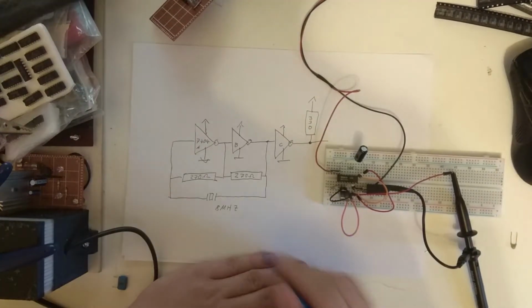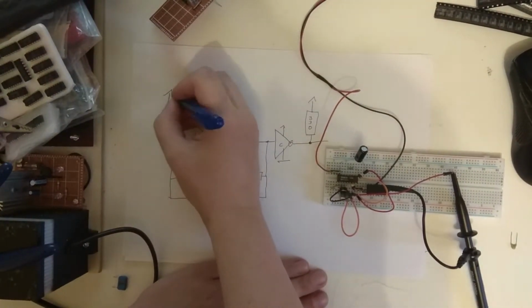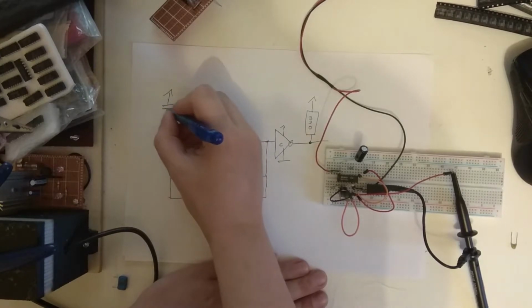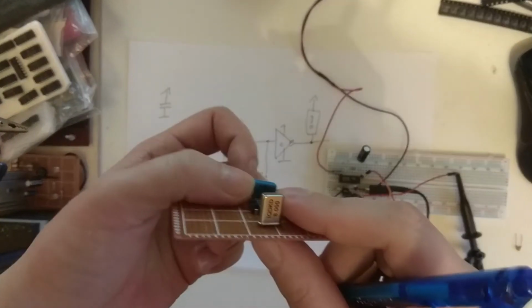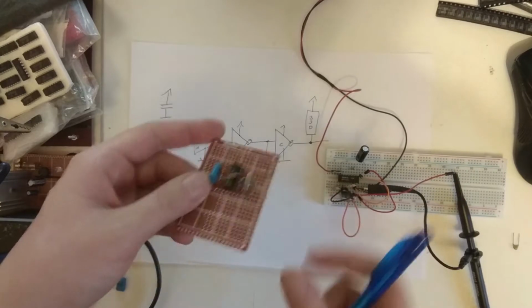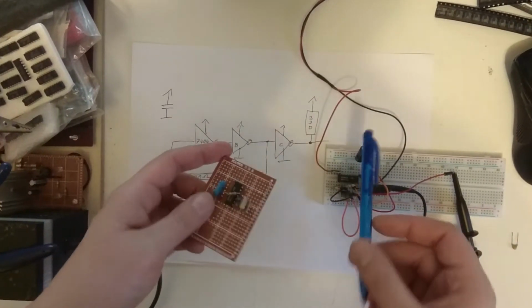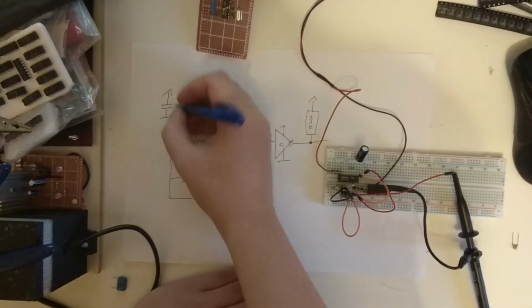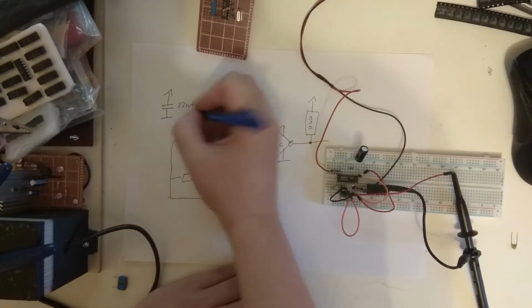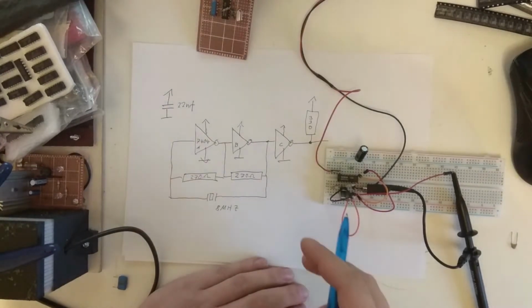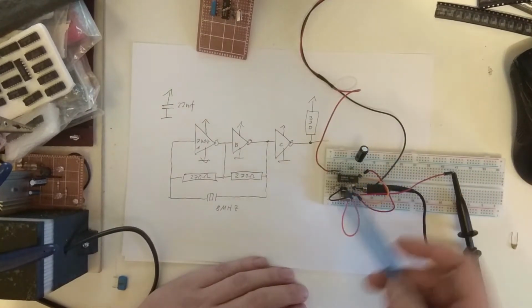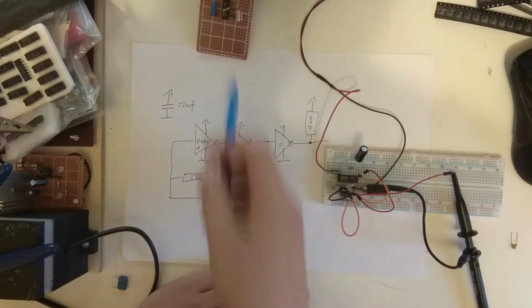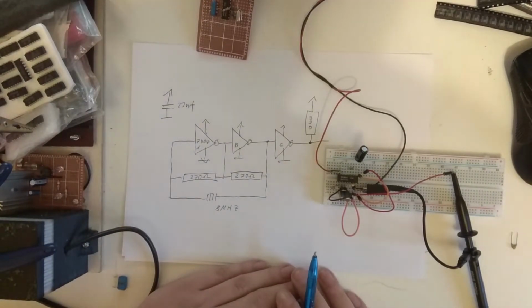So things I did to improve the clock is I put a decoupling cap of, this is actually the one that I took the measurements on. Although there was very little difference between the large decoupling cap and the 22 nano here that I put in. I took some measurements of this, and the oscillation is actually a little worse on this, as you would expect, but it's not great on this either. And yeah, that's just about it.